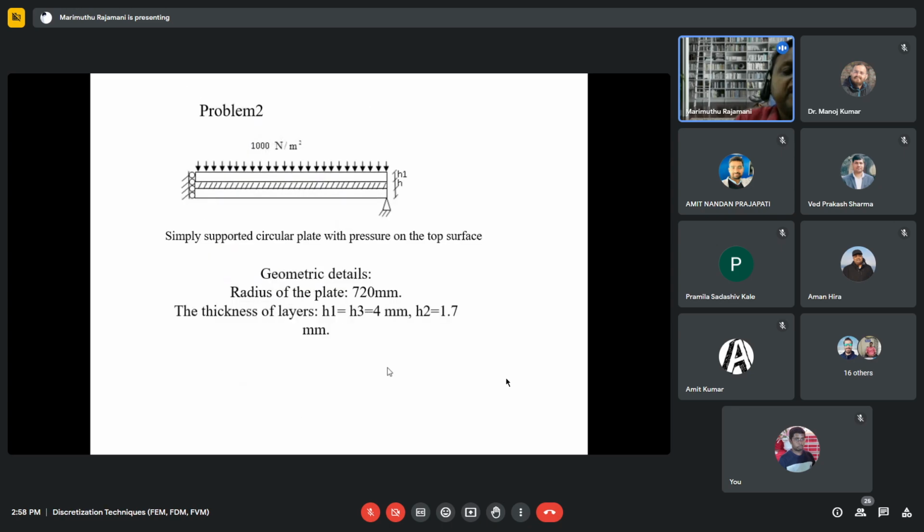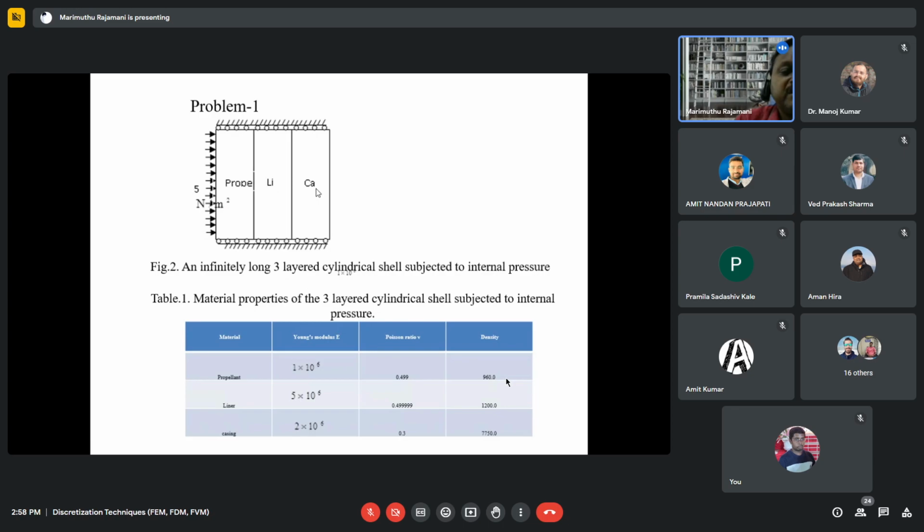And when you apply a harmonic load, you can solve it directly when you express the elastic property in the form of stored and dissipative energy. And when you apply a load in the time domain, you have to bring it into uniformity. For that, you have to transform the loading into the frequency domain and solve in the frequency domain. And the solution you transform back to the time domain to get the proper response. That is the whole content of this dynamic viscoelastic problem in a nutshell.